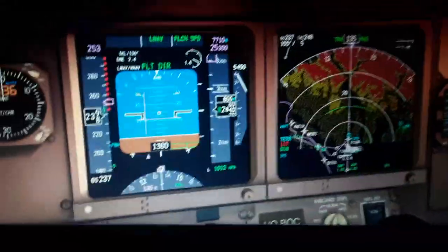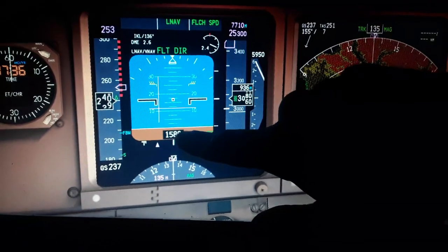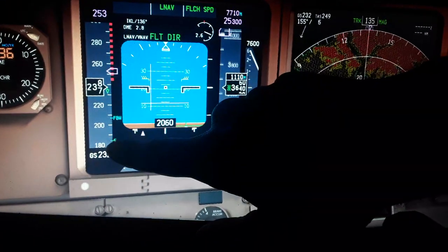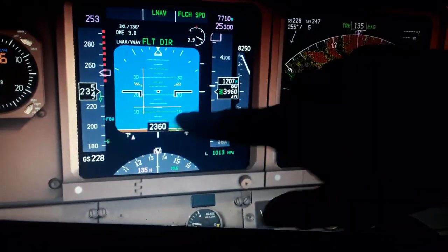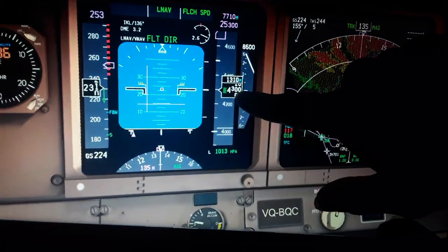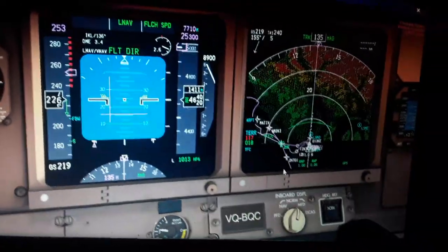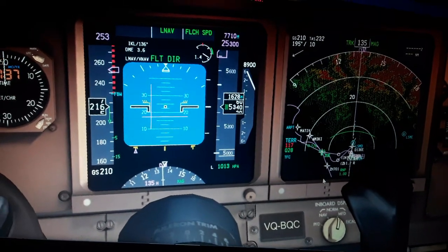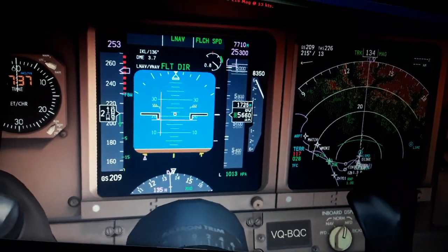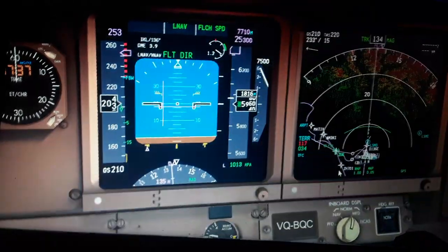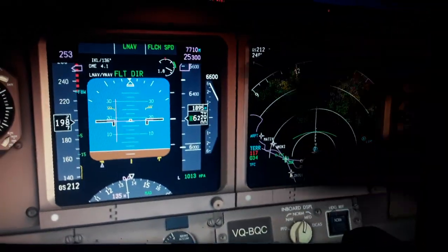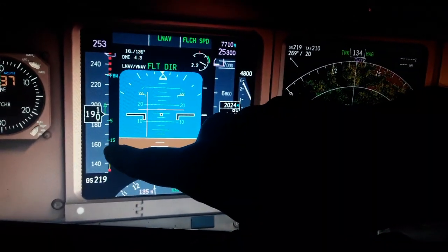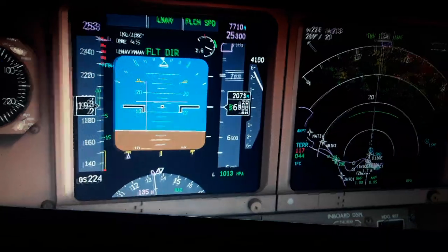So you can see here we are 1,500 feet above the ground level. The airspeed is 250 knots, the stall speed is close here. 2,500 feet above the ground, 4,300 above the sea level. Keep climbing with 9,000 feet per minute. And this is the pitch attitude, about 20 degrees. Now we have to decrease it to increase the airspeed, not reach the stall margin over here, 150 knots.